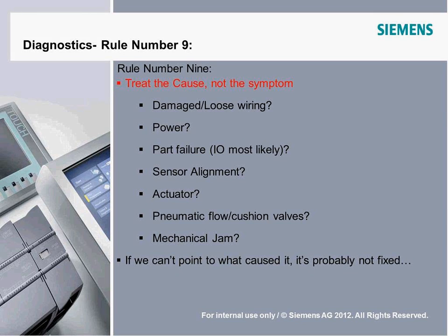For example, if it's a valve or a solenoid valve, it can have problems with a stuck valve. It happens quite often. Dirty air and so forth can build up over time, and the actual valve no longer shifts when it's actuated.